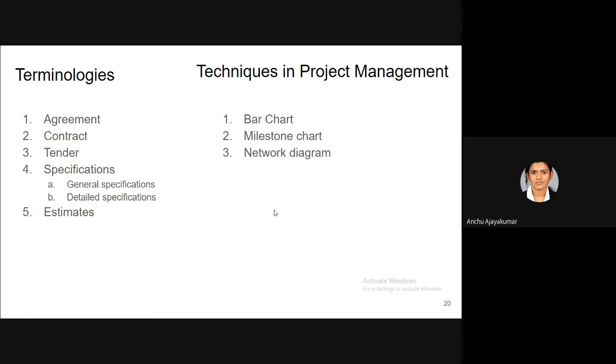So we are moving to network diagrams. That is how network diagrams were developed. These are flow diagrams in which activities or events are connected logically and sequentially. The limitations of the first two, bar chart and milestone chart, are mostly managed in the network diagram. In network diagrams we have two types: activity on arrow and activity on node diagrams, AOA as well as AON networks.